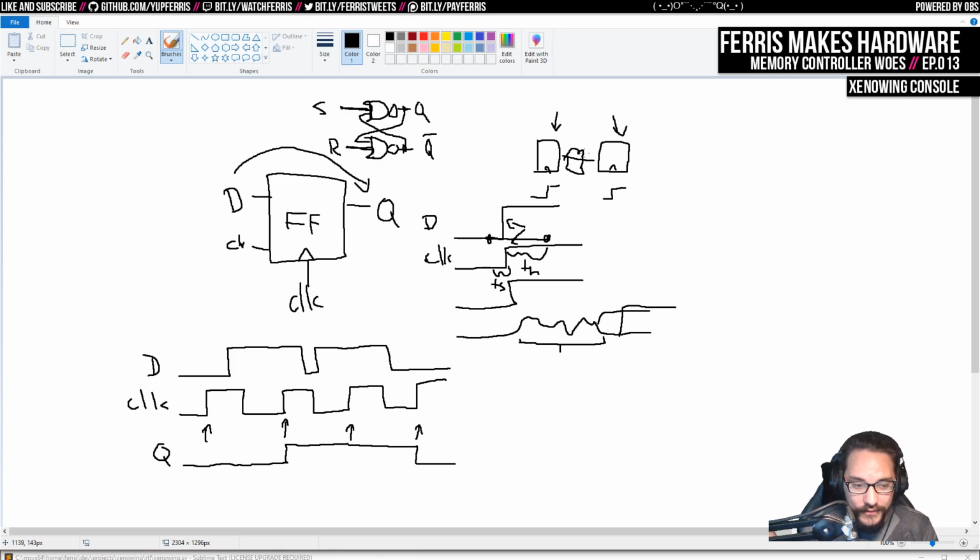And if all of your logic is in the box, if the Verilog synthesizer can see all of your logic, then this isn't a problem because it will understand the constraints. But one of the constraints you need to give is how fast the clock rate is. The part on your board doesn't know, because you know the external part that's going to feed the clock into your device.